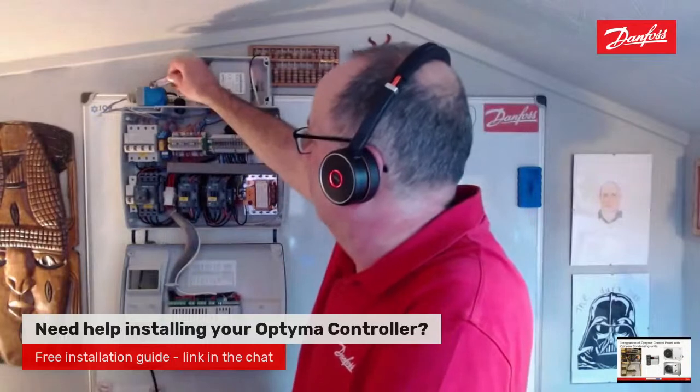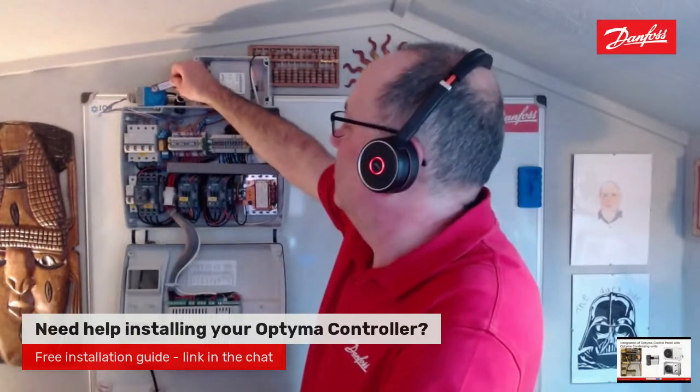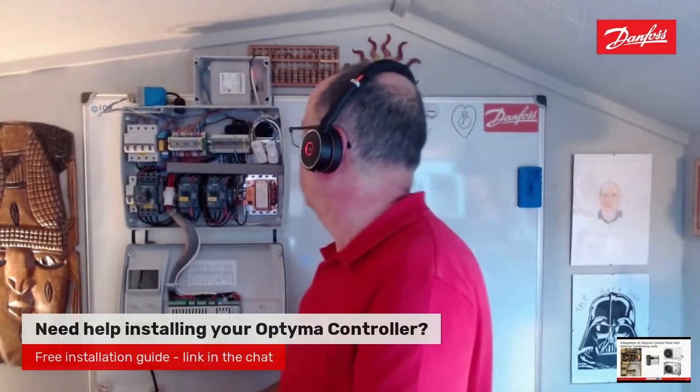I would use the magnetic tool on the Danfoss apps on my phone, but unfortunately my iPhone doesn't have that functionality, so I've got the old-fashioned keyring that we did some years ago. Might still be able to get hold of it. We can see that it is going round, so we know our solenoid valve is energized.